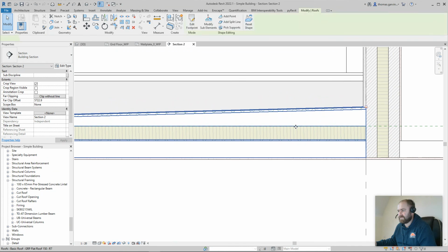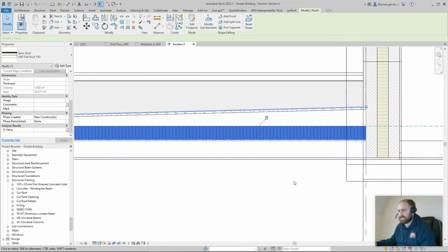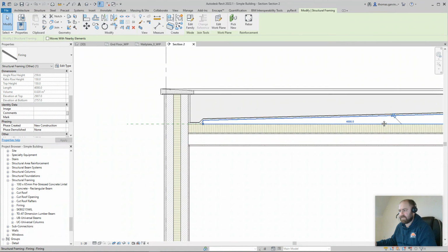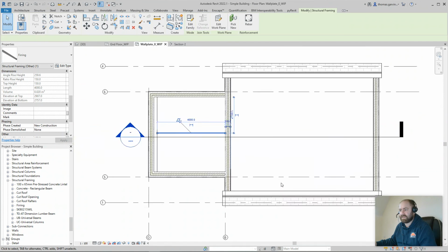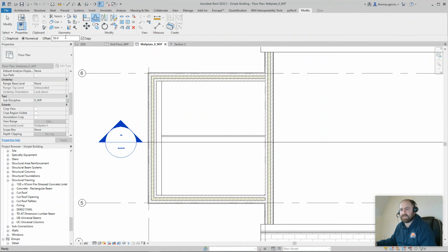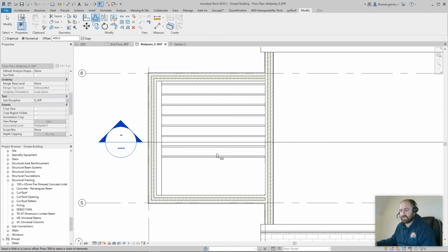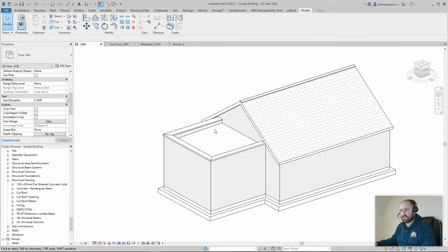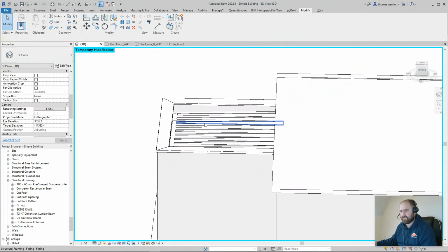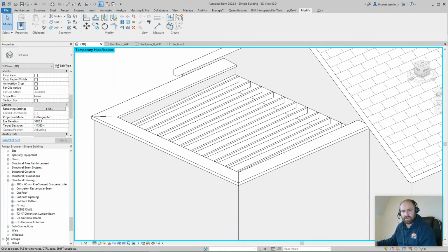There, the roof, and make it wireframe so you can see it. My front piece exactly in place along the roof. And then in wall plate, you can place them by copying, or you could draw again, or you can offset 400, use the offset tool, 400, copy, along the roof. Select the roof and hide it, so you can see, there, furring pieces. Hope that was helpful.